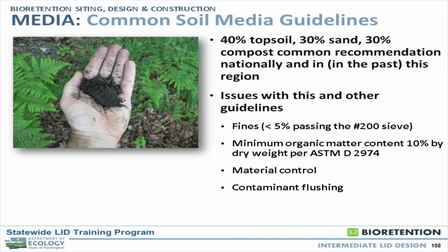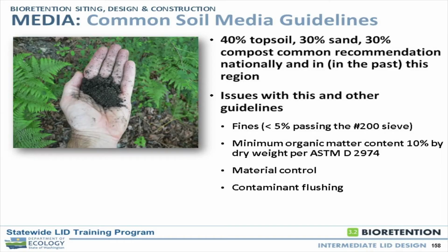There's also been contaminant flushing observed from topsoil blends as well, and the agricultural literature is replete with research showing nutrients, materials being released from agricultural soils when you plow them, when you disturb those soils, right? And that's what we're doing with bioretention media, right? We're mixing it all up, throwing it in a hole, and then expect it to perform immediately. So there's a bunch of issues with the media guidelines and the materials we're using.